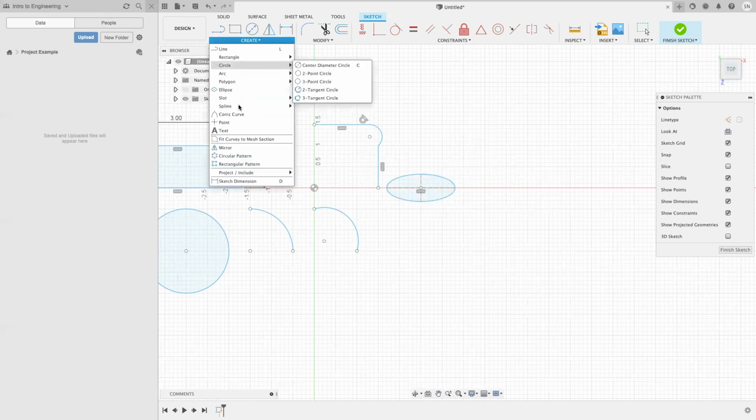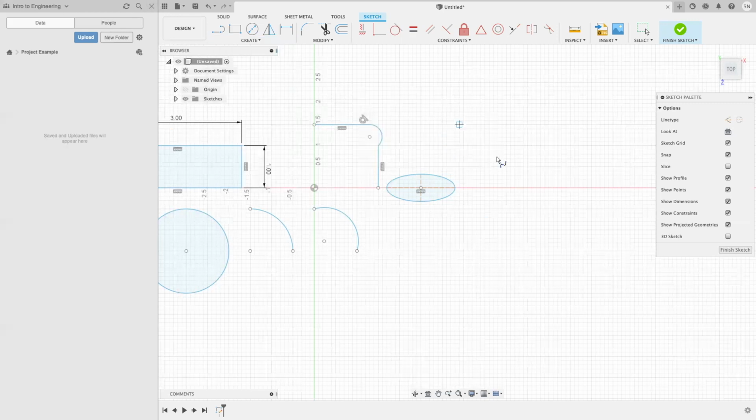Also, you can use the spline tool, which I'm going to go over. I'm going to do fit points spline because it's easier to use. You're going to click, and this is good if you want to make, I don't know, a squiggle, or you can also do an odd shape. So this was just an example of a squiggly line. You can place your dots, and then the lines will adapt and curve to the points.